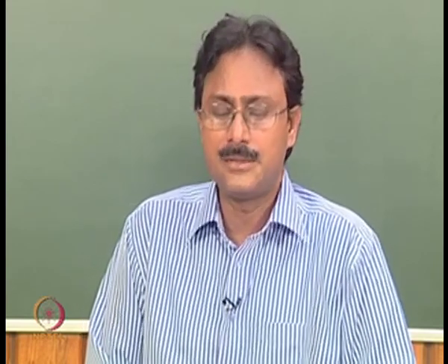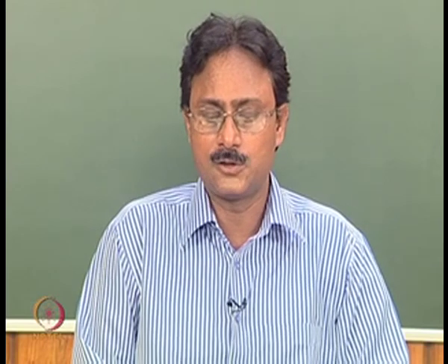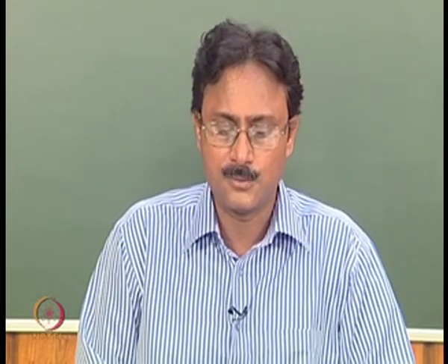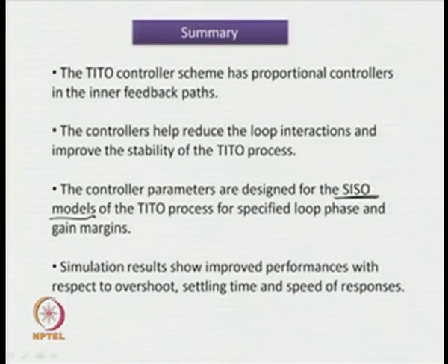The controller parameters are also designed for the SISO models of the TITO process for some specified loop phase and gain margins. Basically, the design technique available for SISO models has been employed to design controllers for the TITO process, and simulation results of course show improved performances with respect to overshoot, settling time and speed of response.